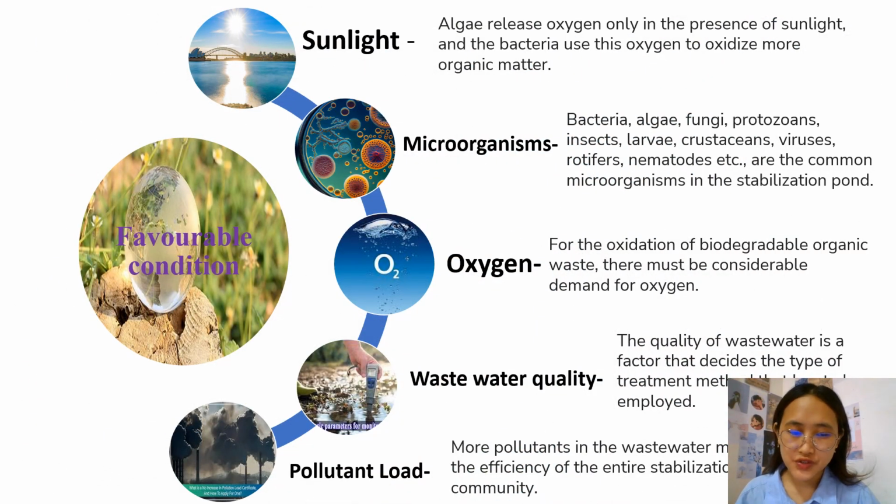The favorable conditions for wastewater treatment. Sunlight: algae release oxygen only in the presence of sunlight, and the bacteria use this oxygen to oxidize more organic material. So sunlight is an important factor. Microorganisms like bacteria, algae, fungi, protozoa are the common microorganisms in the pond, where bacteria and algae help in treatment of effluent, and viruses are removed by the maturation pond.